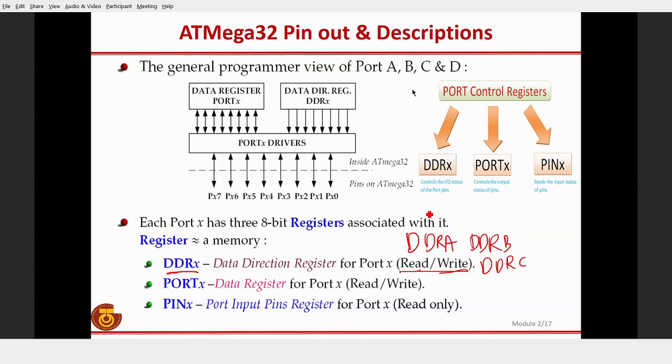So like I told you last time, port A, we want it to be as input. So DDR-A must be assigned with an input, meaning how to make it an input. So all the bits are as an input, right? For example, over here, DDR-A, and there are 8 bits. So we say that we will be using all of port A as an input. So we need to give 0, 0, 0, 0, 0, 0, 0, 0 to all these bits, right? So that tells port A will be working as an input.